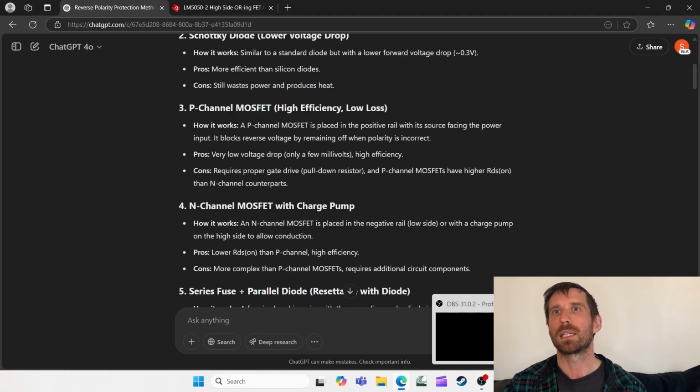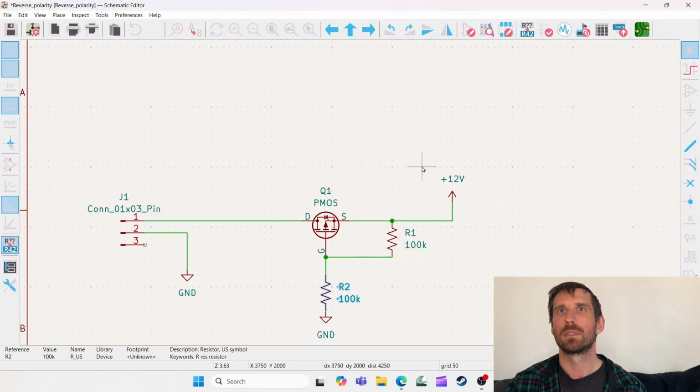So if we go back, okay, if this is 20 milliohms, but what's my current here? It's because you can get these that can do 100 amps. So if I'm at 10 amps, yeah, I'm probably at 0.2 volts if I spec this to be beefy, but you don't have to. So the millivolts can be off depending on your application and how much current you're going to have on there.